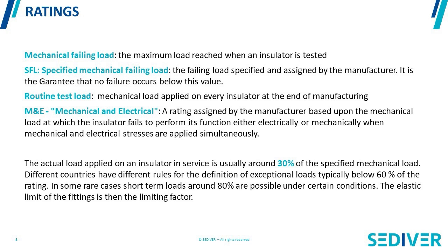Now, you can tell me, okay, we know that the routine test load verifies that the insulator is safe, but if we pull it, don't we create some damage to the insulator? Well, the routine test load corresponds to 50% of the rating, half.